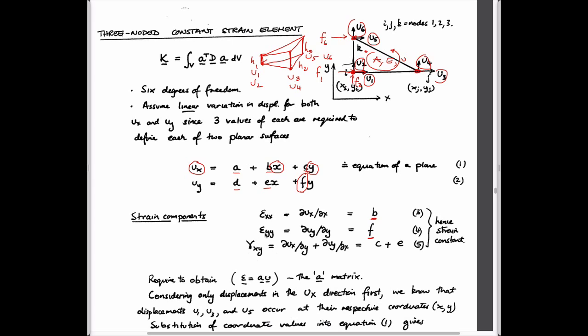And we haven't really talked about this, but by definition, the shear strain is the off-diagonal terms: dux, instead of dx, it's dy, and duy, instead of dy, it's dx. Then the derivative of dux with dy would be this equation and c. The derivative of duy dx is going to be this equation and this term here, which is e.